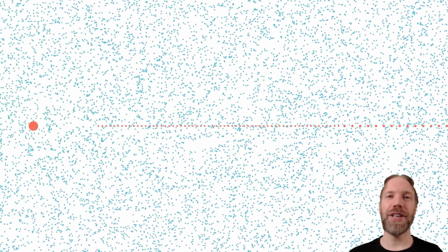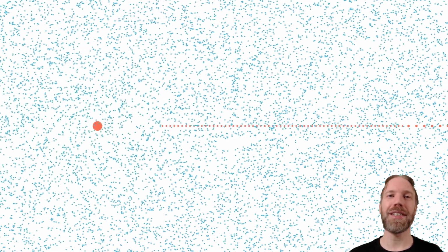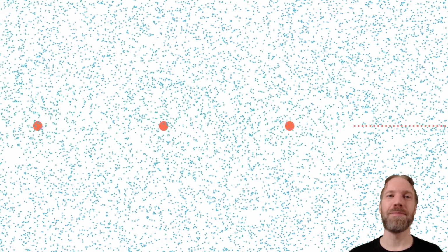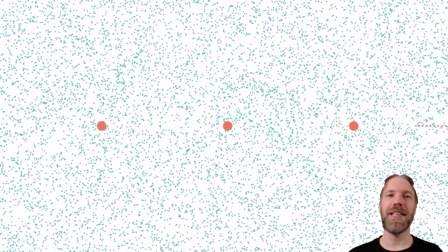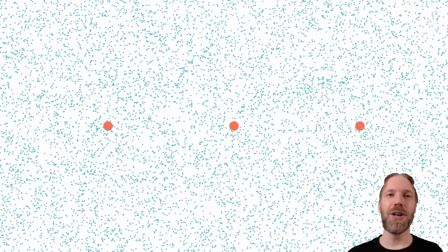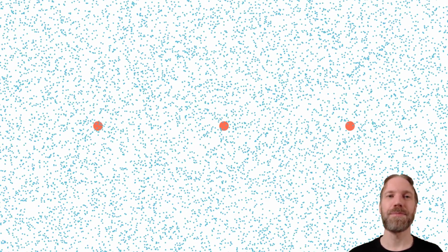If we go back to the original case with the relatively few vortices, we see that the flow is moving up and down between the vortices, which will cause additional losses. The larger the distance we have between the tip vortices, the more significant losses can be expected. Turbines that have many blades and turbines that rotate faster will have shorter distance between the vortices and hence can be expected to have lower losses due to the fact that vortices are separated from each other, instead of a continuous sheet.